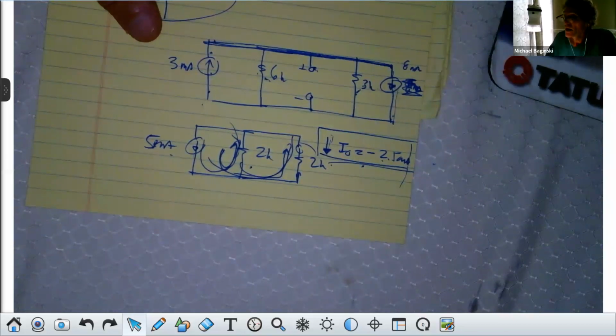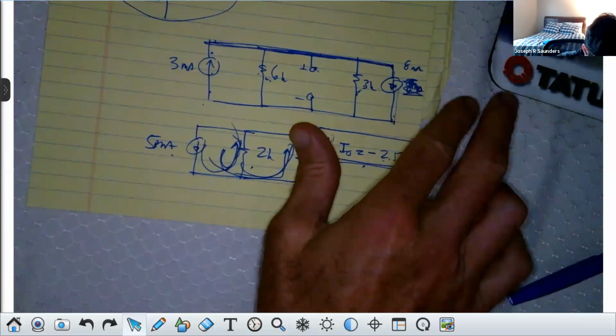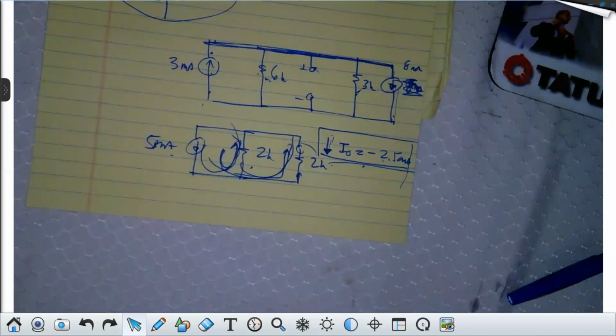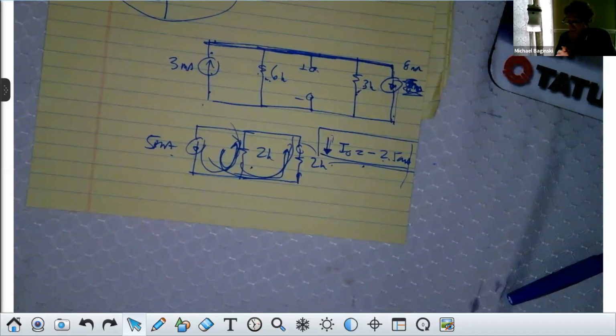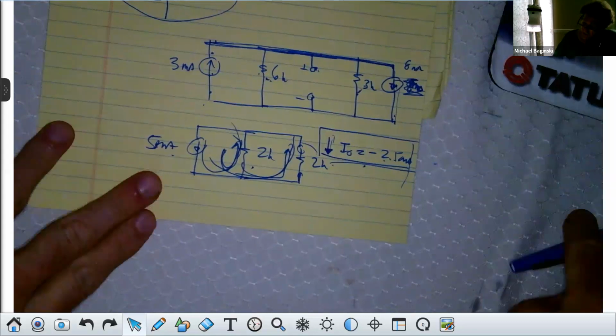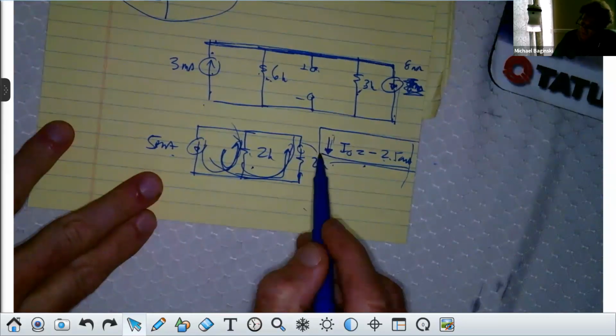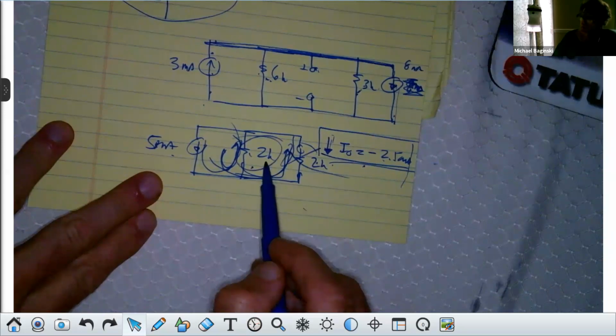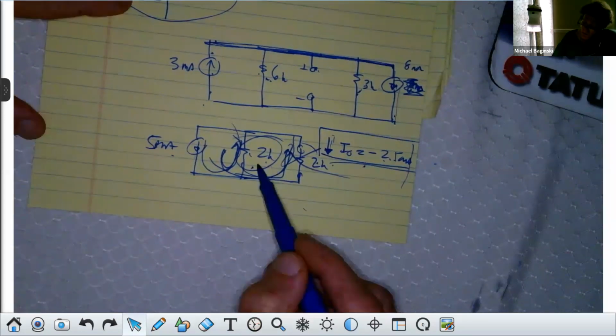Yeah. All right. Next. Now, this is a great thing. It's a good tool to use if you're asked to do Thevenin. You can check your work this way. But this is a Thevenin equivalent circuit right here. If you take this, R Thevenin, now remember, you get that out of there, R Thevenin would be 2K, right? Actually, I would convert it to a voltage source.